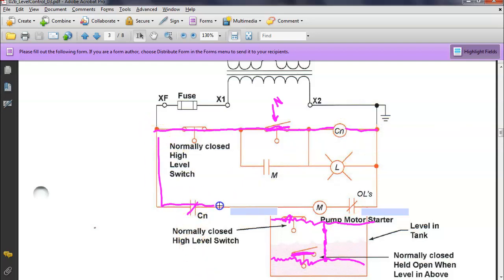Now what's that going to do? It's going to bring in our motor. Our motor starts running liquid, but as soon as this comes in, it's going to close that contact right there. So what did you just do? It just sealed itself in, right? Just like y'all did in motor control. Standard seal-in circuit, but this seal-in or this memory circuit is done automatically once we start this thing running. So as soon as you put power on this thing, guys, something's going to happen, right?